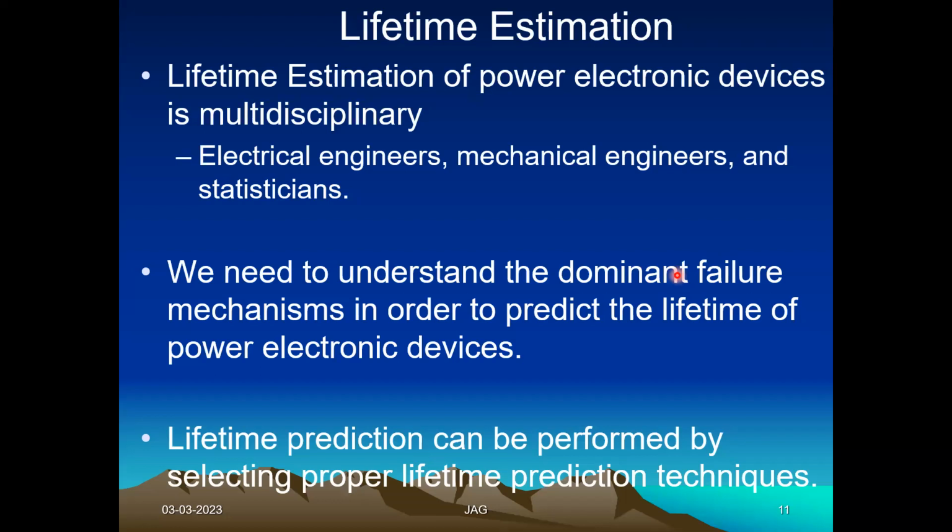Another possibility is to circulate some fluids around the heat sink, or the inner part of the heat sink carries some fluid. That fluid will absorb the heat energy better than the surrounding air. That is guided by a mechanical engineer. That is why I have told you that for the reliability assessment, the mechanical engineer is important.